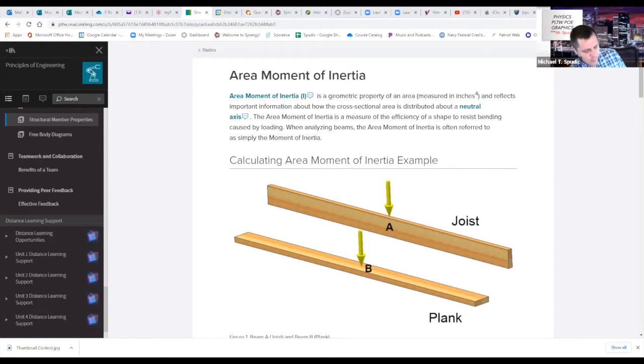Okay. So the reason a joist is used for the floors as opposed to a plank, and if they're the same exact thing, is that a joist is going to be more sturdy. It's not going to bend as much. If we had it as a plank, when you walk the plank, right, that will bend a whole lot more. And it's literally the same exact piece of wood. It's just turning it on its side. And now all of a sudden it's strong.